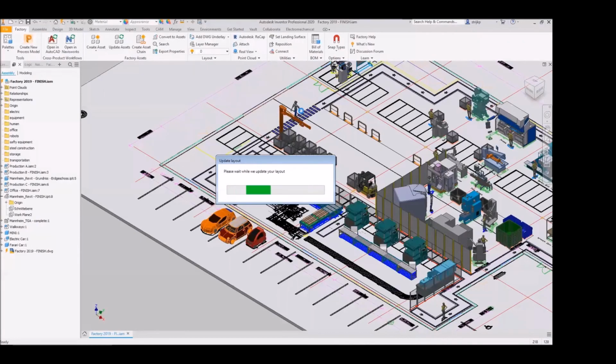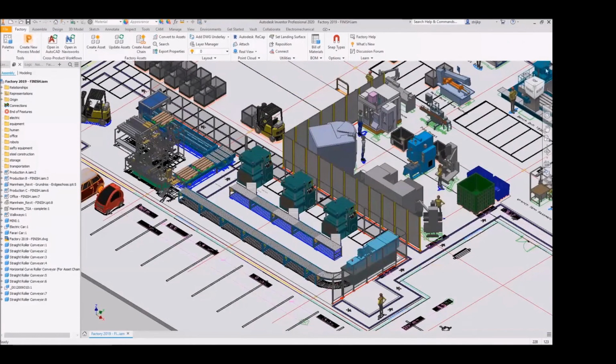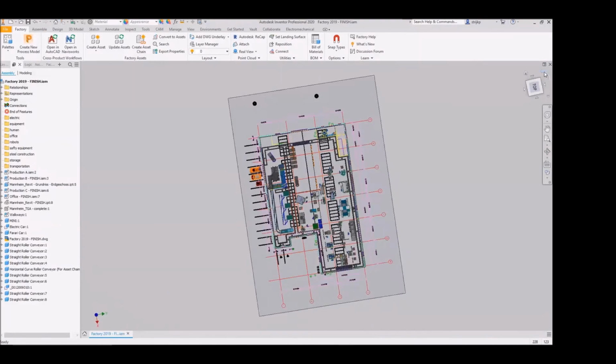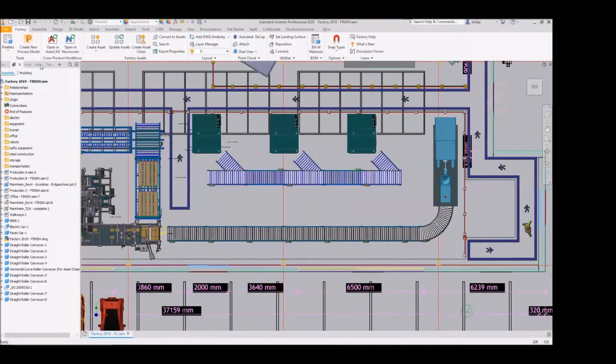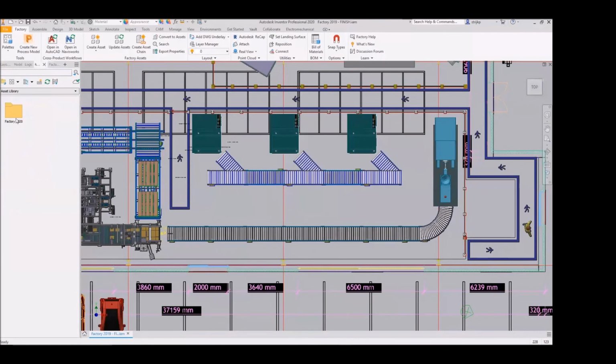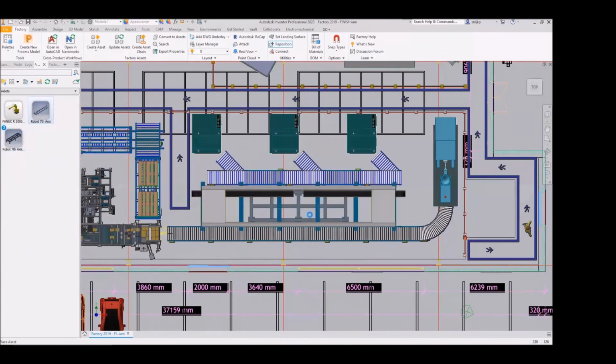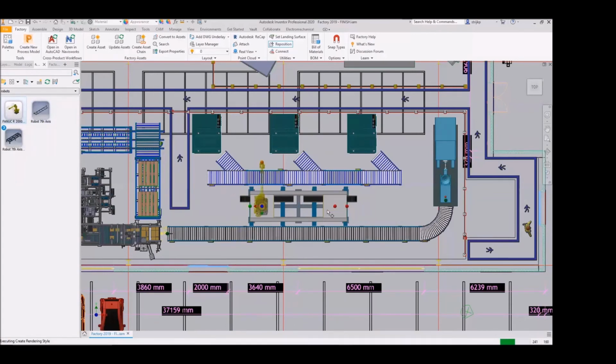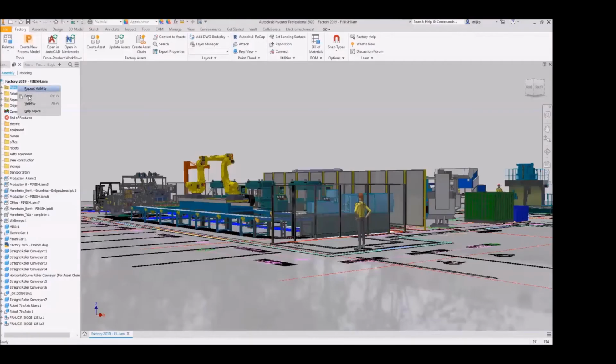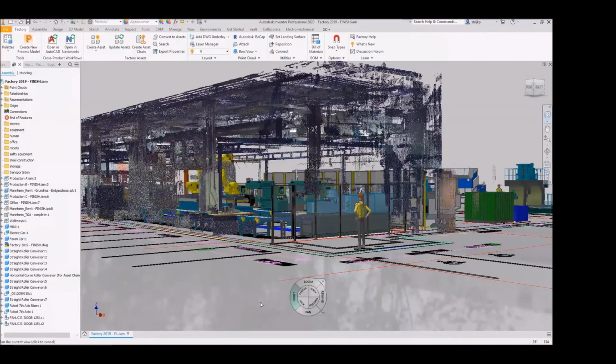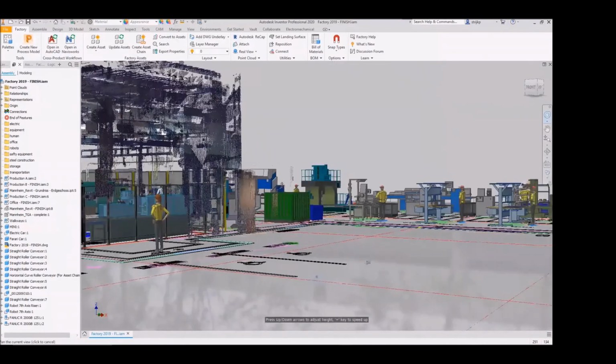And inside of Inventor, that 2D layout is going to become 3D. So you can see our factory in 3D over here. And we can then place assets again, the same asset browser. And this time we're going to look at robots. So we're going to place down a robotic stand, and then we're going to place 2 Fanuc robots on top of it. And we'll snap the one into place, and then the second. So what you'll notice with factory design is that we can sort of snap these components together.